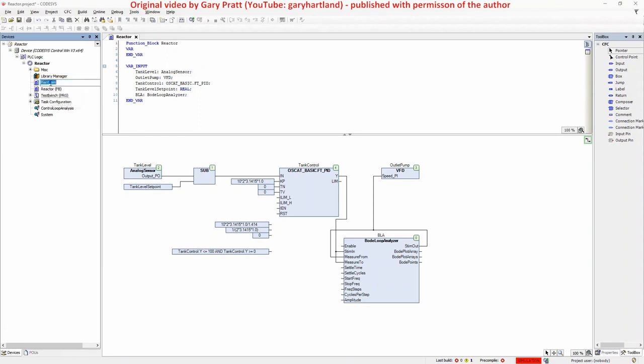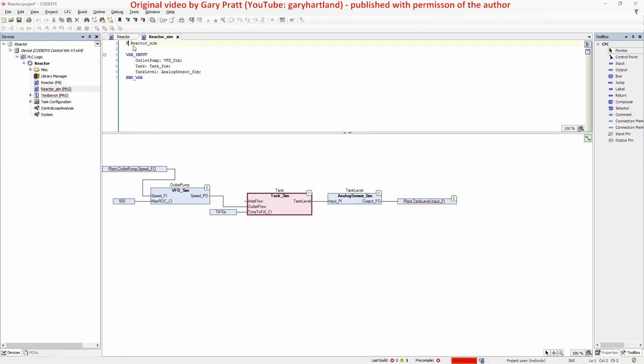We do the same for plant sim, but we also need to add a pointer to a reactor, so each instance of plant sim knows what plant it's connected to. In IEC 61131-3, a VAR_IN_OUT is a pointer under the covers. Then we need to change the hard-coded I/O to associate them with a pointer which will be passed to the simulator when it is called. If you don't completely understand this, it will make more sense in a few minutes. We will call the pointer myReactor and swap that into the I/O path names.